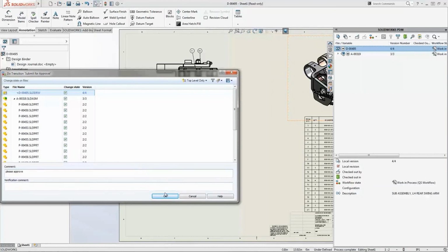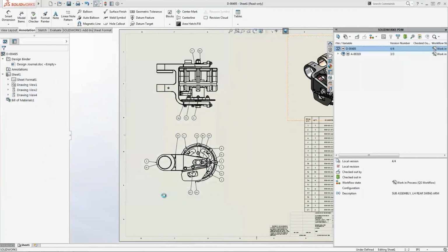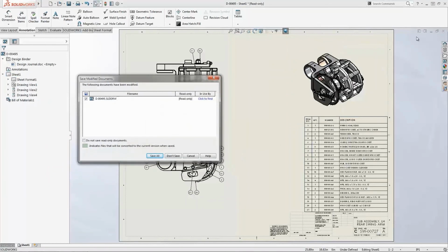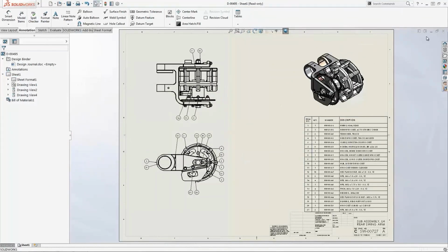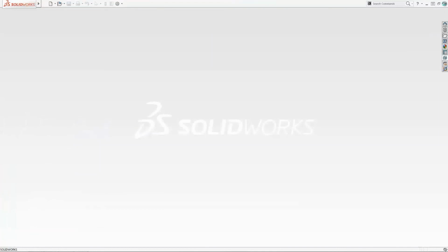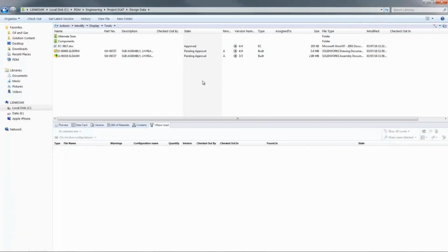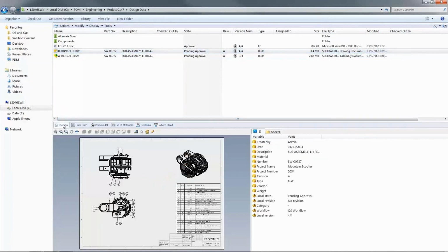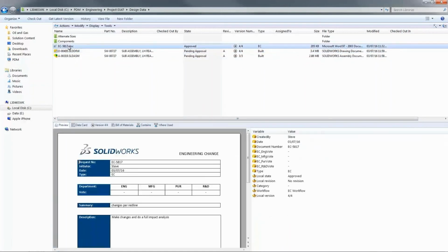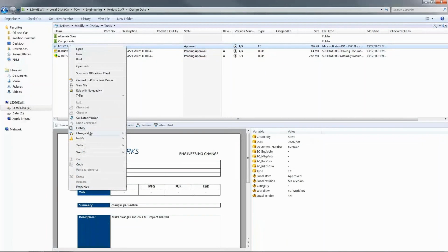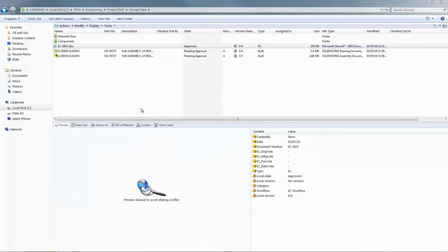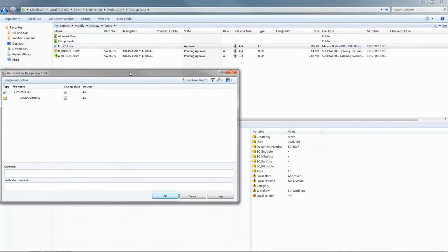When I'm doing this, the manager will give final approval to release the document as a new release, with revision B automatically created. And you can see here, if I refresh, I will see now that this is the final approval. Okay, the manager will approve the file, and then this is the ECO. Change state, design approved. Just like this.